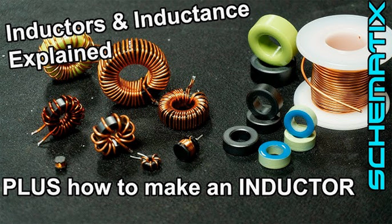Audio systems crossovers. Application. Inductors are used in audio crossover networks to filter out high frequencies, directing low-frequency signals to woofers and subwoofers. This helps optimize the performance of different speakers in a sound system. Example. In a speaker system, an inductor may block high frequencies, allowing only bass frequencies to reach the woofer.